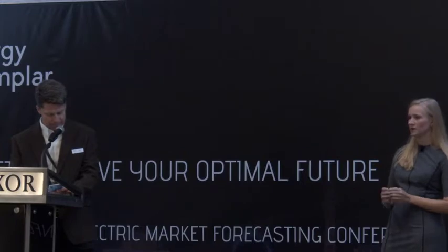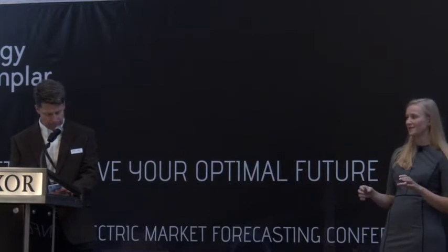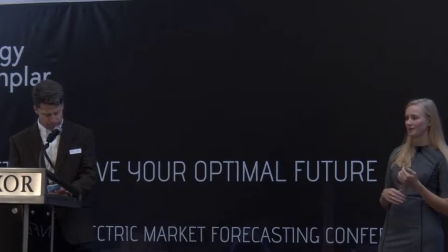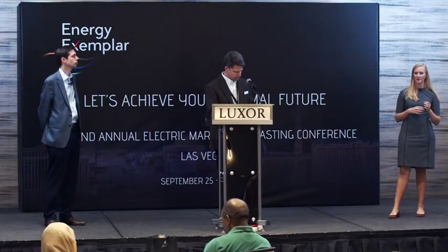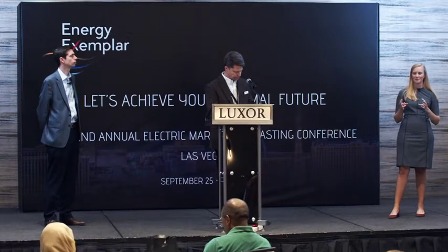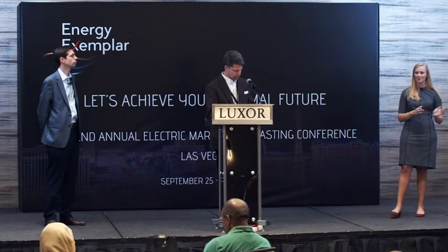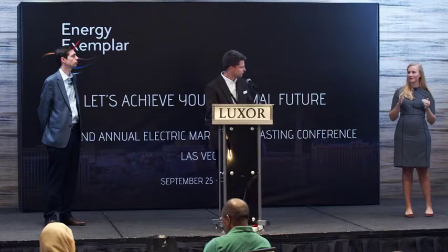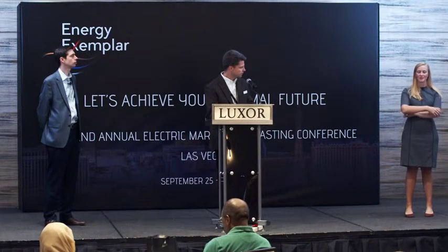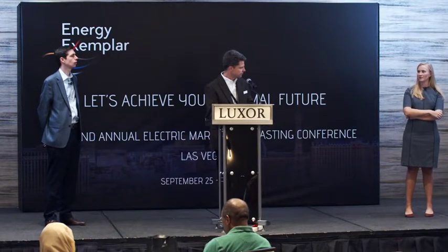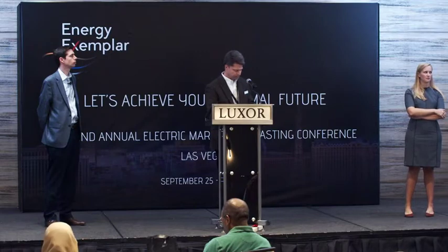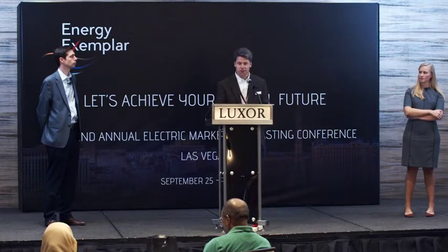Sure. So we're trying to keep them equal on a UCAP basis. So it basically means we're paring back the amount of solar and then adding, basically, on a nameplate basis, 25% of the solar capacity as storage, and leveling that out on the UCAP so it meets that 8% reserve margin. Yeah. So for the 2-to-1, you would see less solar, more storage.